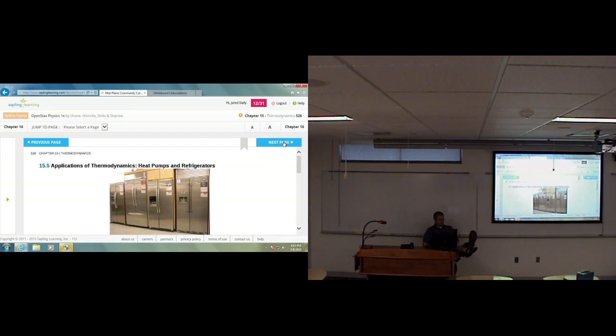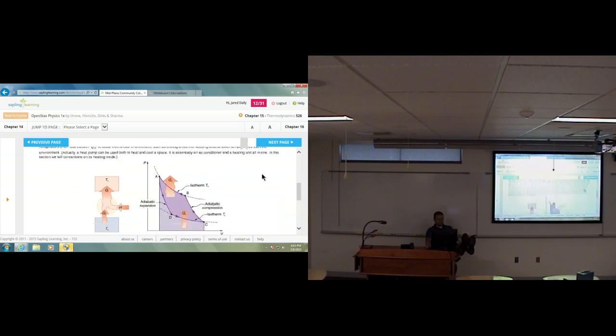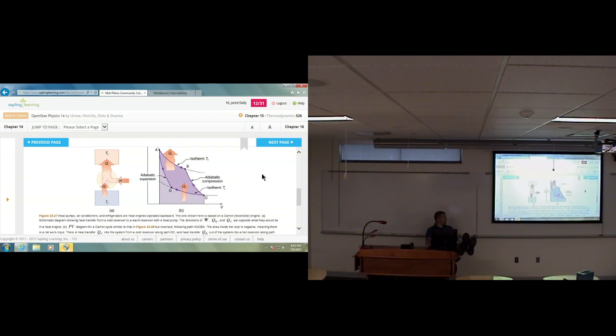The work due to friction, for example, inside the generators, inside the turbines. That's all energy that's lost and can't be turned into electricity because it's lost in the process, not in the thermodynamic process, but in friction processes. Leaks in the system itself, actual fluid leaks, steam leaks, those cause problems. And that's what power plant operators essentially spend their time doing: monitoring those things, fixing those things, and maximizing the efficiency of their power plant.